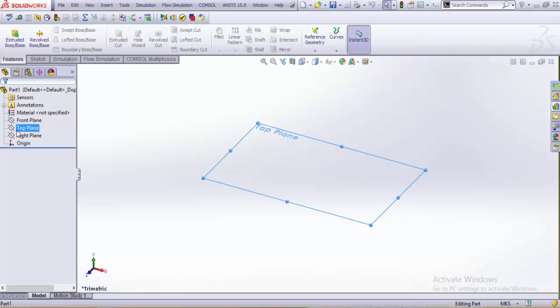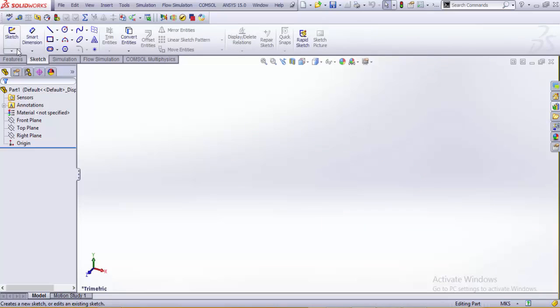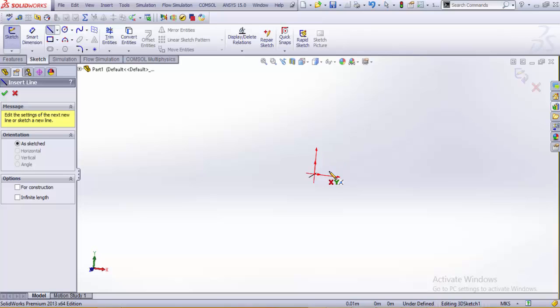For that, at the initial stage, we go for tubings, and we might just need a 3D tubing system. For that we start a 3D sketch, and we can start any sketch in any direction. Let's say we want an open network, but before that I want you to observe that the cursor activated for the line has the corresponding plane written as a subscript near the pencil.